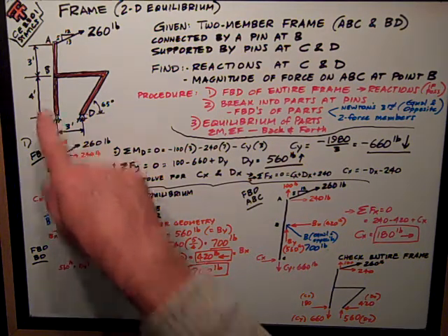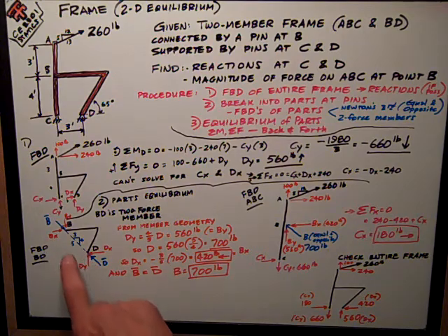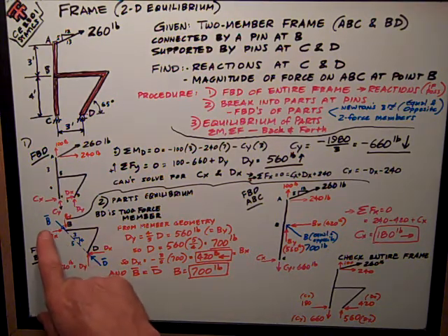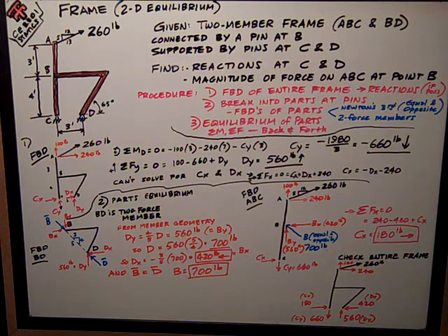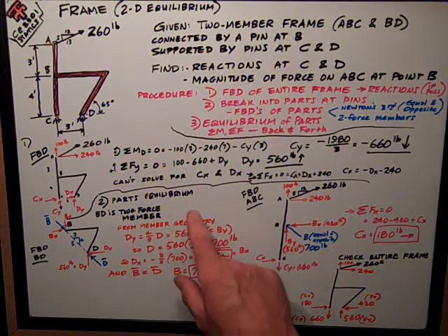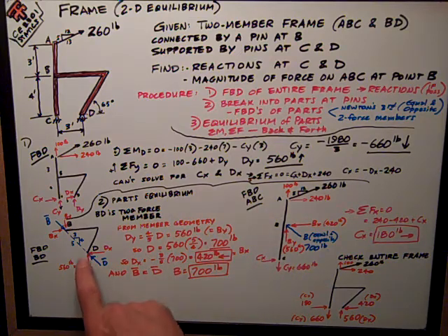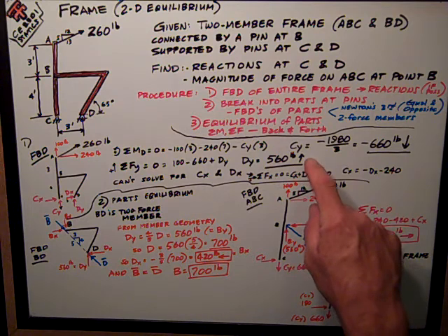That from the geometry is a 3, 4, 5 line, and so I know that the force at B, which I've resolved into just one force, and force at D, have to be equal and opposite and collinear. So from the member geometry, I know that that has to be a 3, 4, 5 relationship, just like the member geometry.